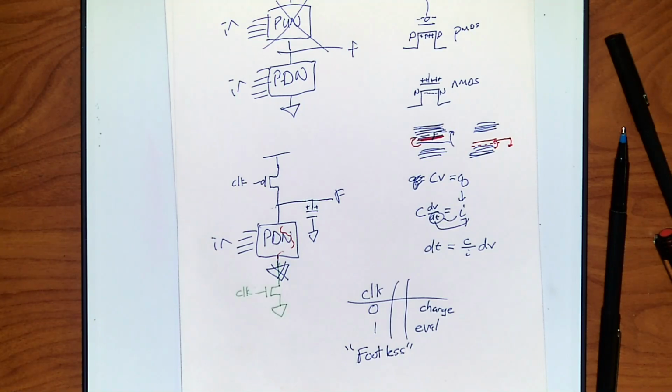We also run into this situation when the next stage is called the same clock. It's going to open up. And if it's not hard pushed here on the output, it will, across that resistor capacitor network, take a little while for it to charge up. It might be too slow to reach the next stage.